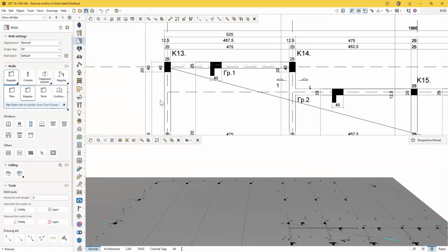If you have a situation like this where you're doing one wall on one side and then one wall on the other, you will not be able to put any kind of door opening or anything like that. These other tools do not work very well with the thin walls. So you're going to want to use this regular wall. A thick wall is the same as a regular wall, but it comes in a little bit thicker. However, I find that usually even a thick wall is not exactly the size that I need it to be. So I'm going to need to use those stretch nodes to adjust it anyway. So to really save some time, I just use my regular walls.